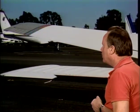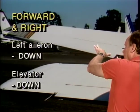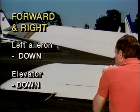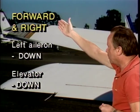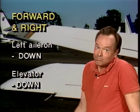Now, you might guess, will they ask you anything else about this? Yes, they're going to ask you what happens if you move the wheel forward and to the right. So here we are moving the wheel forward and to the right. When we do that, we're trying to turn the aircraft to the right, so this left aileron will go down. We're pushing forward on the wheel. We want to go nose down, so the elevator will go down. So if you move the wheel forward and to the right, the left aileron will go down and the elevator will go down. The FAA figures that's a good idea for you to know that, so when you hook up these controls, you do them right.